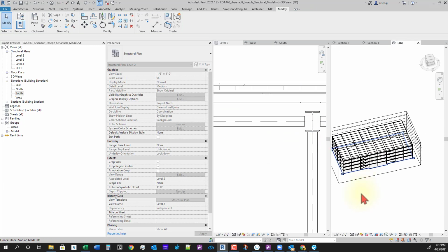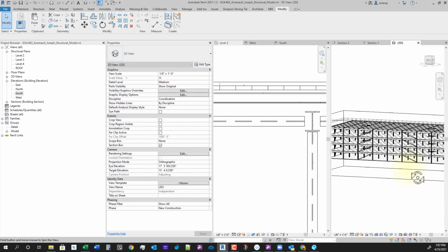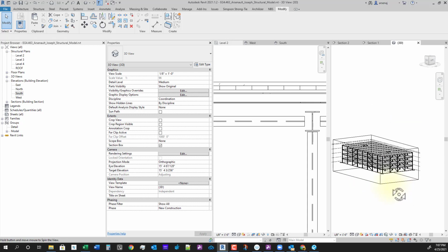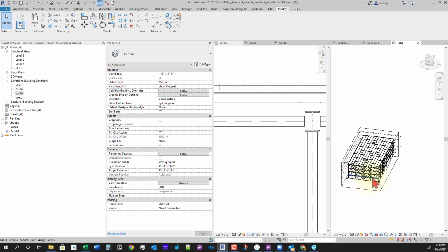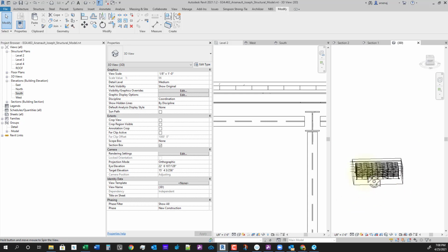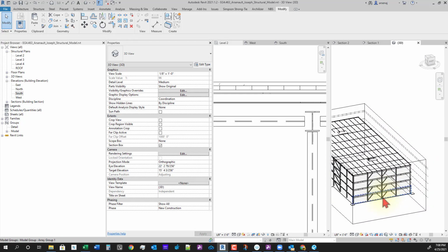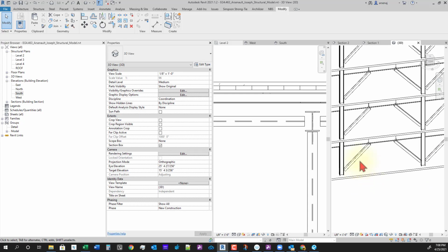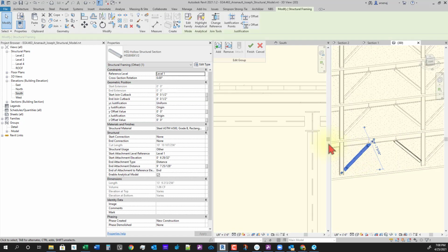And now we are starting to get more structural elements, frames. So these brace frames, I'm going to come in here and try messing with that ratio again. I'm going to change it from distance on the ones on the end to ratio. And I'm going to do 0.1, 0.9.